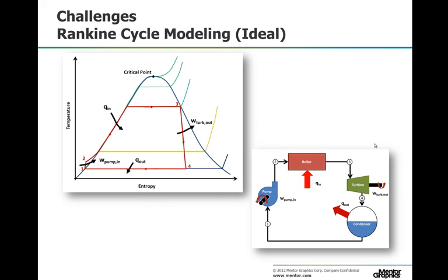One of the key requirements of two-phase flow modeling is to properly simulate the complete Rankine cycle. There are 4 processes in the Rankine cycle. These states are identified by number in the diagram on the right. In the process from 1 to 2, the working fluid is pumped from a low to a high pressure. As the fluid is in liquid state at this stage, the pump requires little input in energy.